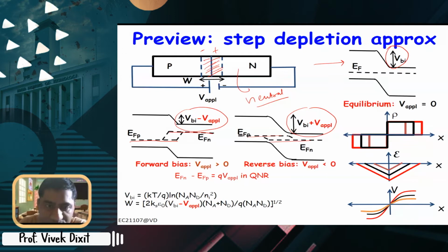Now notice one more thing here. This is the P type Fermi level here, so its full P concentration is there. But if you go through this depletion region, your hole concentration decreases, right? What about electron concentration? Here electron concentration is the full N type concentration, but if you move from here, you see the gap here. This gap is small, this gap is large, right? So electron concentration decreases here. So this is the transition region where electron concentration and hole concentration decrease. But their product is not Ni square. Their product will be related to the exponential of the difference of these two Fermi levels.